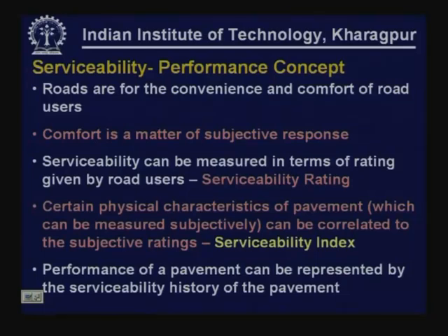This is nothing but the rating that would have been given by the panel if the same panel had gone to the particular road. But instead of taking the panel to the road, the actual serviceability rating that would have been given by the panel is estimated on the basis of relationships that have already been developed between the serviceability rating given by the panels to different roads and the corresponding physical measurements made on those roads.